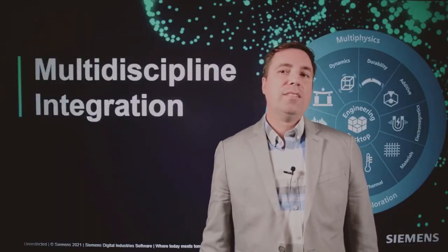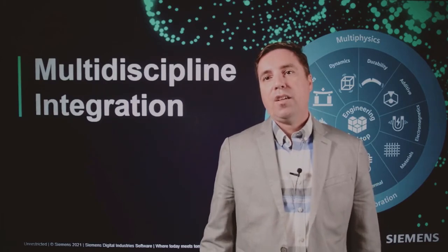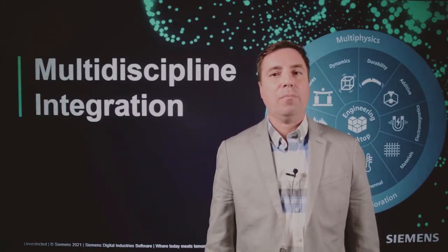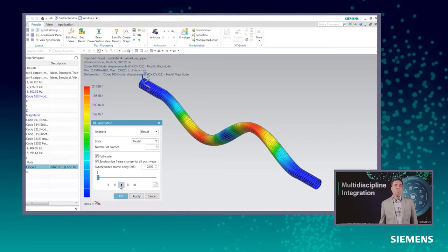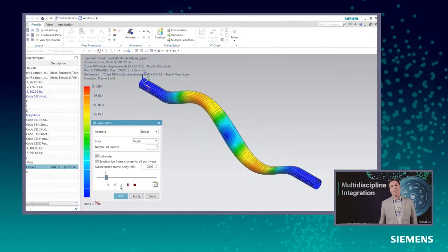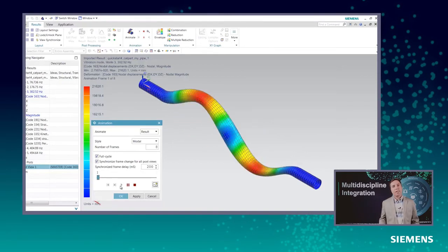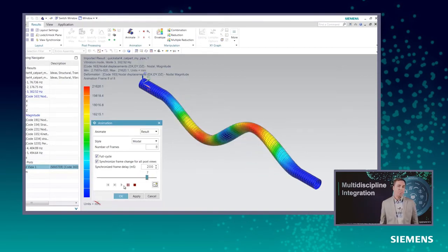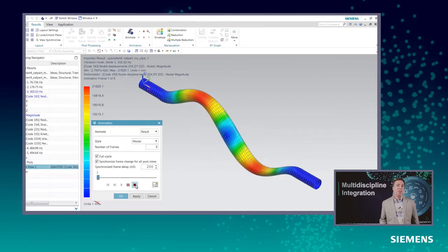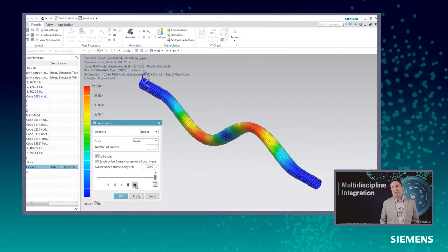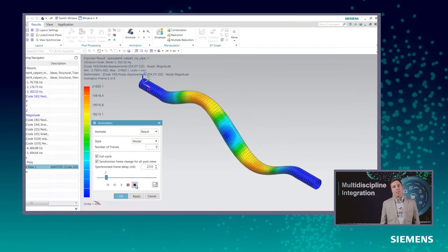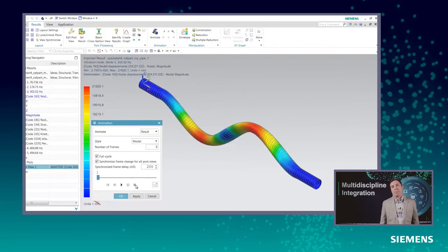For those of you who design and develop flexible pipes and hoses, such as brake hoses, you're probably already familiar with or maybe even use Simcenter 3D Flexible Pipe. Simcenter 3D Flexible Pipe allows you to simulate mounting scenarios, calculate initial and operating positions, and calculate forces and moments within a hose. In addition, it can be used to validate designs by checking for excessive curvature or collision with other objects, and even look at crushing.